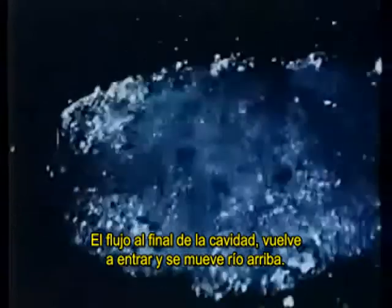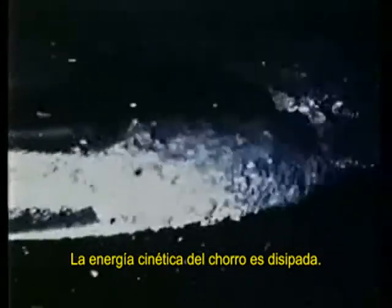The flow at the end of the cavity re-enters and moves upstream. This re-entrant flow is illustrated more clearly in the cavity trailing our supercavitating hydrofoil. Re-entrant flow is characteristic of such cavity flows. The momentum flux in the re-entrant jet is equal to the pressure drag of the body. The jet kinetic energy is dissipated.